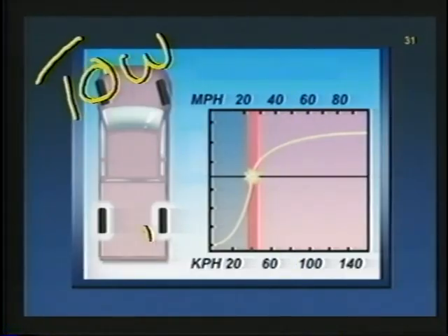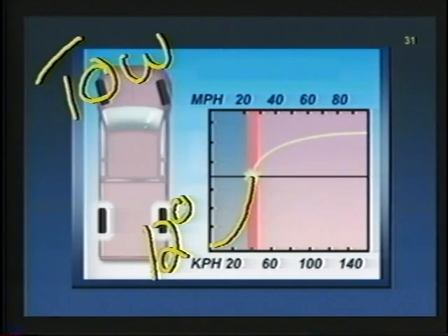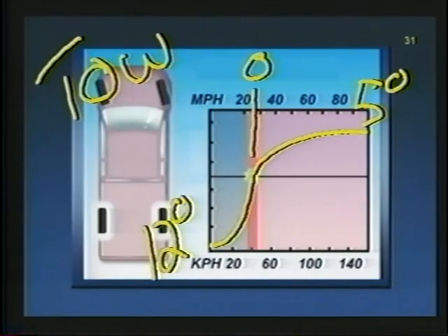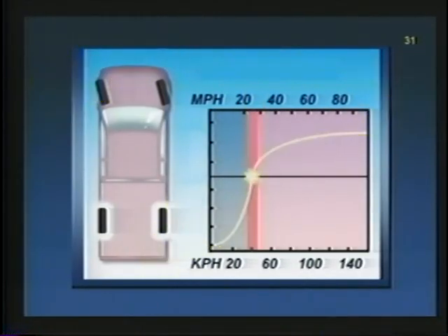Now in the tow mode, we still have 12 degrees here. That's our negative phase. But you see very rapidly from that 12 degrees at very low speed, we're dumping that turn radius off. By the time we get to this 25 miles an hour, we're back to 0. Then we cross over into the positive phase, still with 5 degrees here. So the amount that we're turning the rear wheel really hasn't changed at all, just where we make the transition. That's going to change: 25 miles an hour instead of 45 miles an hour.